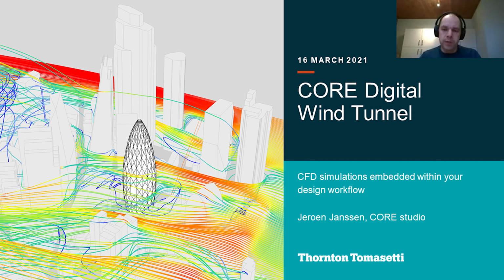The most common type of wind tunnel testing is that you put a solid, rigid body in the wind tunnel. You measure the movement over time, the dynamic forces on the building, basically on one point on the base of the building. And you then extrapolate that back into a dynamic response and accelerations and the frequencies of the building.